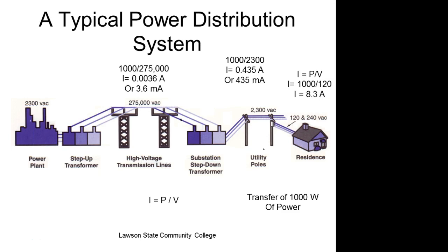We can step it up for transmission, right? You understand? Because I'm not trying to sell you voltage, I'm not trying to sell you current, I'm selling you power. And the higher the voltage I use to deliver that power, the less current is required, which means I'm going to be what? It's going to take smaller conductors. Basically, it's going to save me money on conductors and also make them easy to install. Are we okay there? That makes sense?